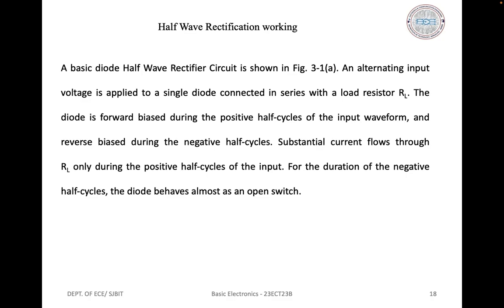Power supply performance is defined in terms of the output voltage stability when the input voltage or the load current changes. Other important diode applications include clipping, clamping, DC voltage multiplication and logic circuits. Diode clipping circuits are used for clipping off an unwanted portion of a waveform.